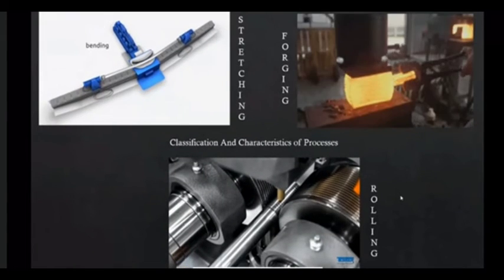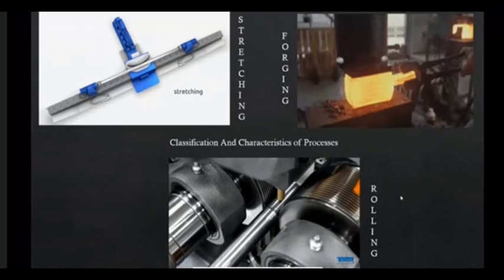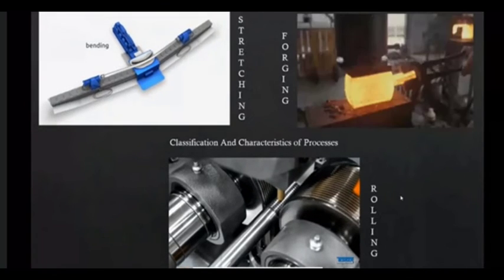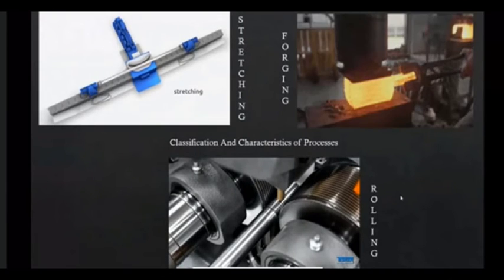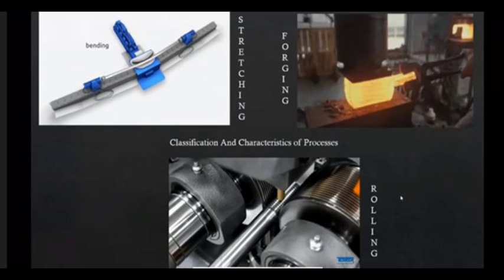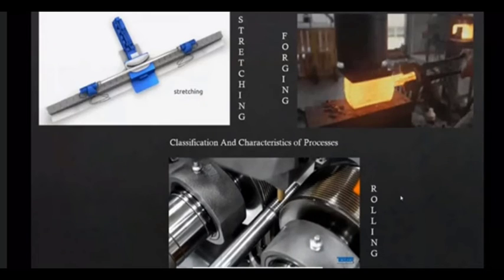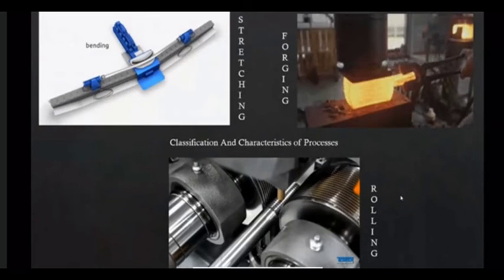In both cases, the surface of the deforming material and of the tool are usually in contact, and friction between them has a major influence. In bulk forming, the input material is in billet, rod, or slab form, and a considerable increase in the surface to volume ratio occurs in the formed part. In sheet forming, a sheet blank is plastically deformed into a complex three-dimensional configuration, usually without any significant change in sheet thickness and surface characteristics.